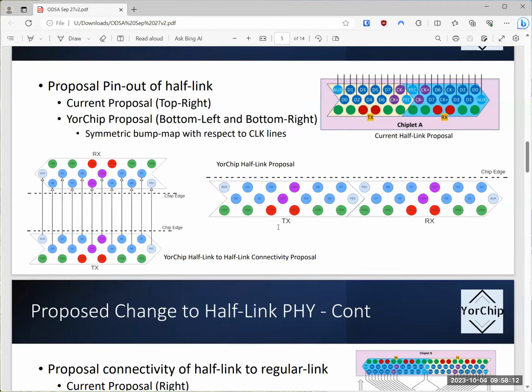And so what I was attempting to walk through was, when do you care about that difference and what does it do to you? You care most if you have a whole bunch of these repeated along the die edge, and you accumulate that skew, right? That's when you care the most. It's just that I suspect, I could be wrong, that's a fairly infrequent case, because most likely if you have a lot of die edge, you wouldn't do a lot of by 8s, you'd do a lot of by 16s anyways.